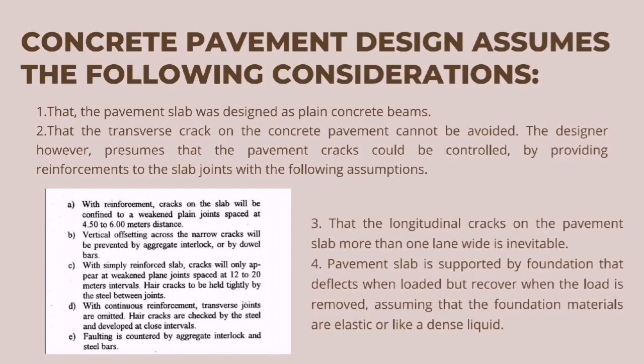Third, that the longitudinal cracks on the pavement slab more than 1 lane wide is inevitable. Fourth, pavement slab is supported by foundation that deflects when loaded but recovers when the load is removed, assuming that the foundation materials are elastic or a dense liquid.